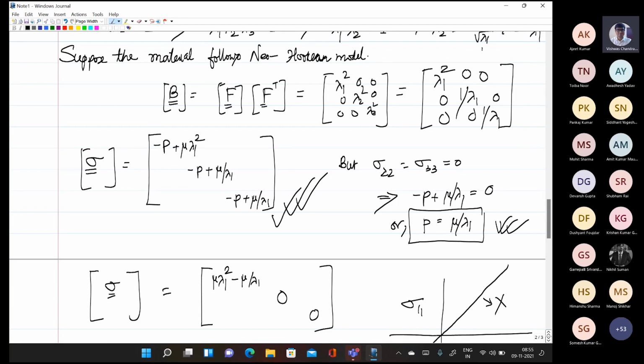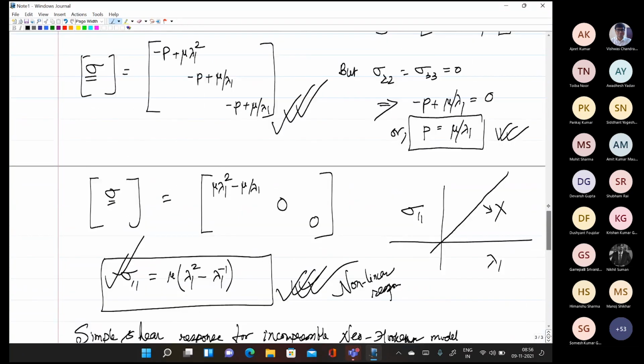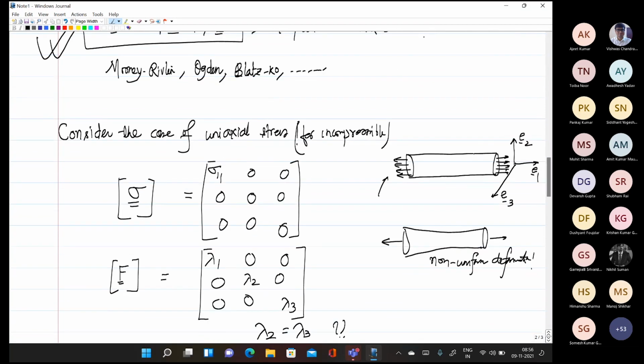Sir, in this case of uniaxial stress, can we not think of some uniaxial pressure P being applied over the area? No, because that is sigma 1 1. Sigma 1 1 is the internal response, but something external must apply it, which has to be equal to what you're applying externally. Because this is a beam, the internal response here will be the same as what you're applying externally at the ends. So that's your sigma 1 1.